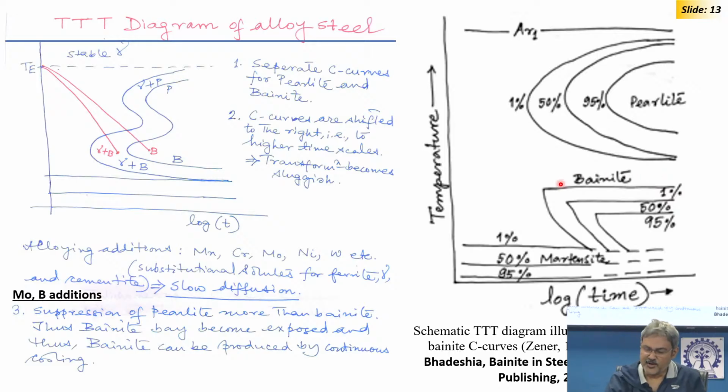So, because displacive transformation dominates the nucleation, here you see a flat curve like in martensite, because what is required is to activate some defects to form the nuclei, right? Some amount of undercooling is required to activate say 5% defects, which you can consider as the nucleation of bainite or nucleation of martensite. If you cool further to a lower temperature, even 50% defects will now nucleate.